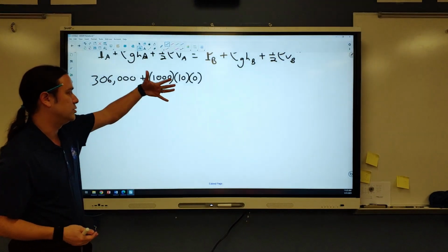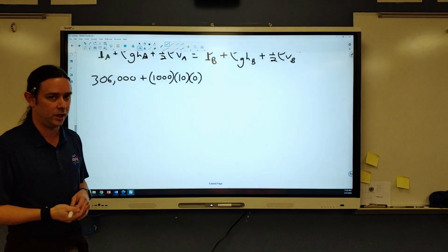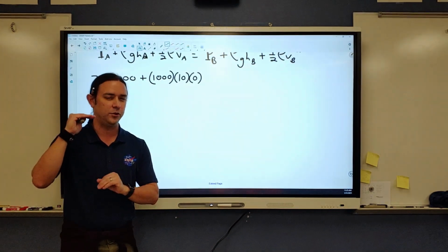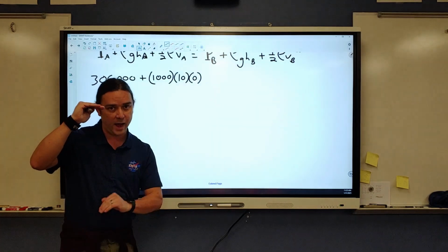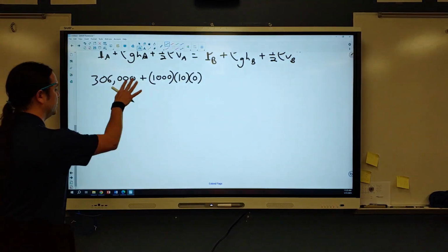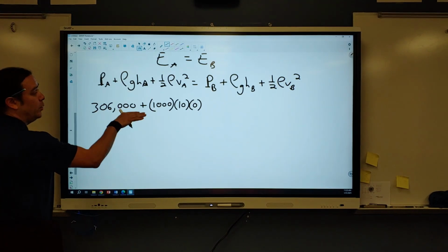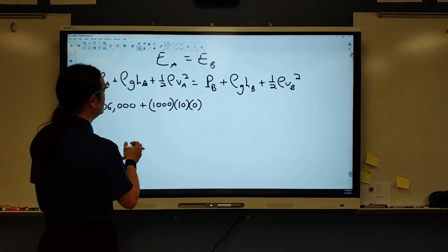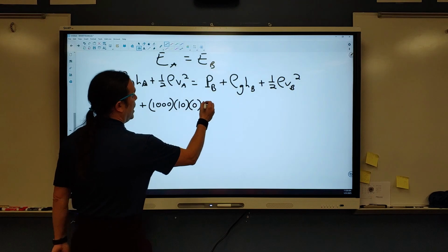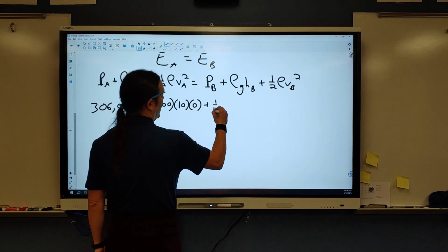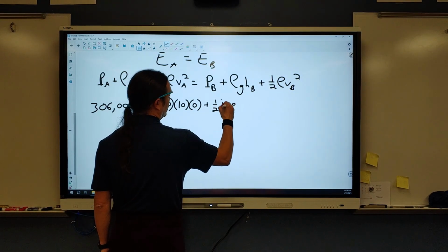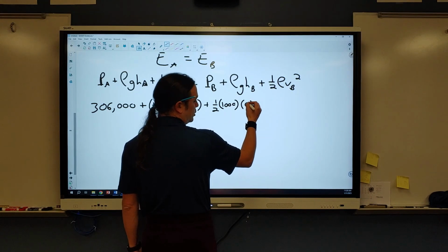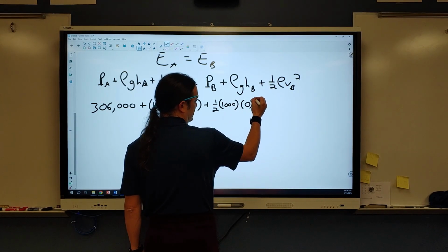In this case, the hydrostatic pressure starts to get a little bit trickier, since we had introduced it as the height below the surface. That's if you're just dealing with what it is down at the bottom of some sort of depth. But since we're applying energy here, all we need is to be consistent so that we can see what we've got here. Okay. So now that I've got that, I now have plus 1/2 rho, which is 1,000 kilogram per cubic meter, times v_A squared. Well, I said that basically our flow speed there is effectively 0.